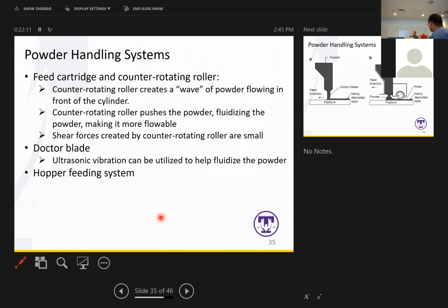So what you do, with every part, is print a little tensile test coupon right next to it. There's been talk about that, but even that doesn't give you all the answers, because you get different properties based on your location on the plane, and based on how thick the plane is. So you print tensile test specimens all the way around the outside of the part and some inside of it. But if you've got something that requires 100% testing, it doesn't matter. There are certain things where, once you follow the code, every item is going to be tested, so you might as well use that. Yep. Yeah, that's probably the biggest challenge for any of this.